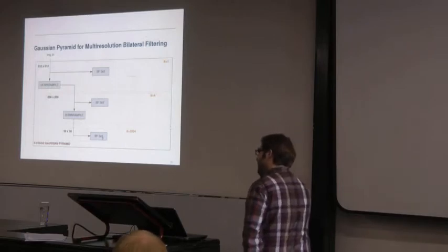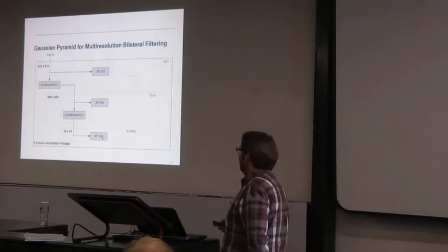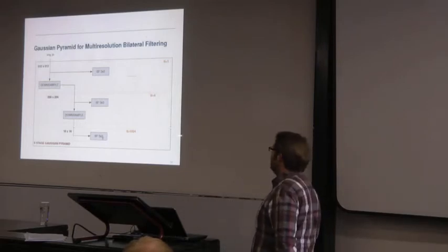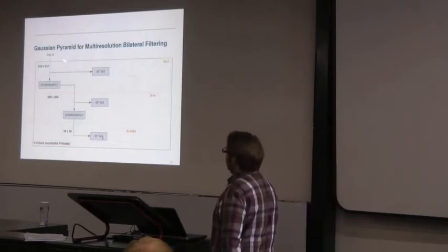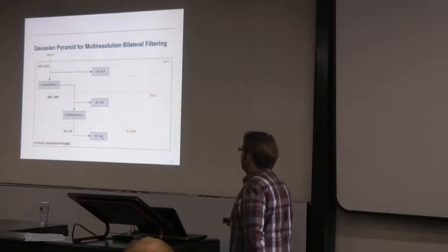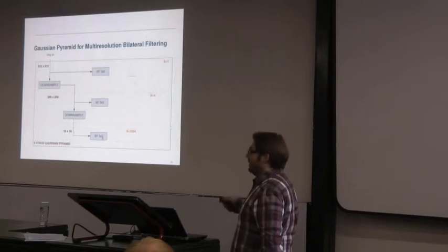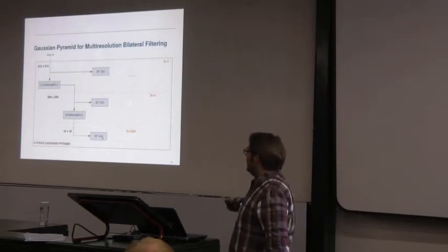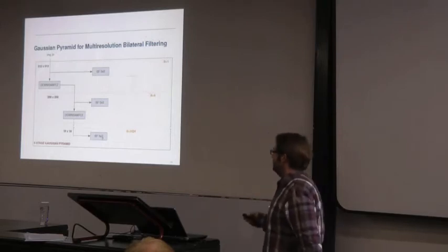So what we can do, we can either supply its own clock and cut that clock by 4 to make it run in synchronous mode, or in high-level synthesis, much easier, we can just increase the iteration interval by forcing it, for example, to 4, so that these two stages can run completely in sync. And for the next levels, this goes down to actual 6 levels. On the lowest level, you do not have to perform any more downsampling, so we can simply run the bilateral filter and have an iteration interval of 1024. Up here, we need a dedicated operator for each operation. Down here, we can make use of operator sharing, because we have the larger iteration interval.